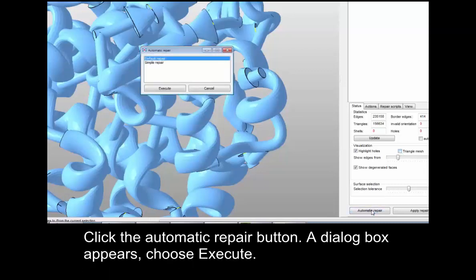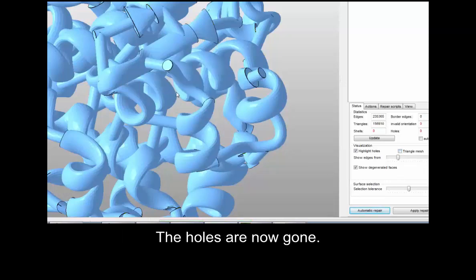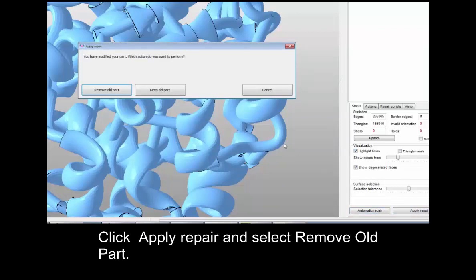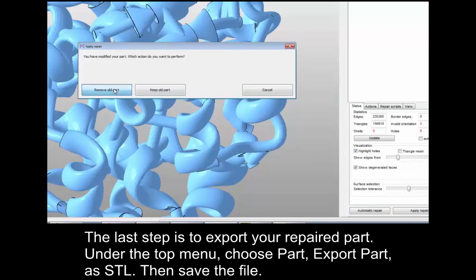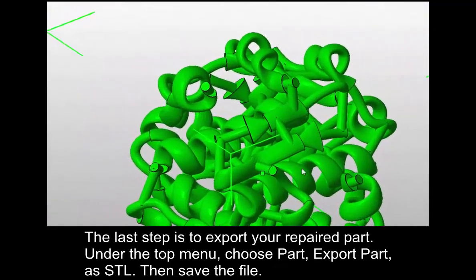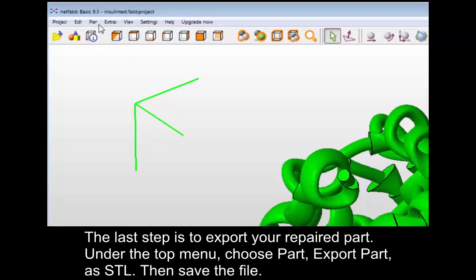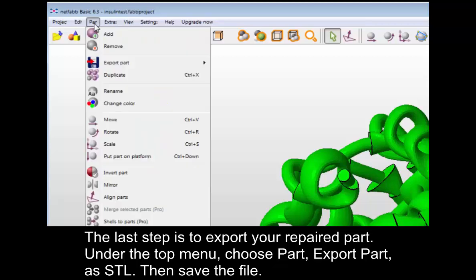Click the Automatic Repair button. A dialog box appears. Choose Execute. The holes are now gone. Click Apply Repair and select Remove Old Part. The last step is to export your repaired part. Under the top menu, choose Part, Export Part as STL, then save the file.